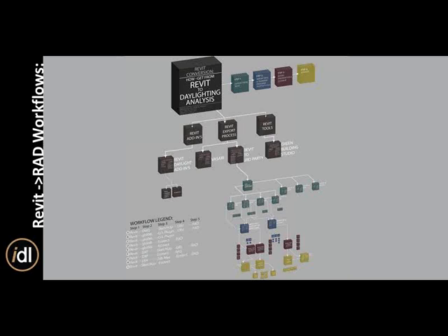Yeah, it's interesting. Opening up the gbXML file, there's only a certain number of parameters that get exported from that material layer in Revit. And Lauren showed like 5 different tabs of properties, right? So it's inherently a simplification that just currently doesn't include surface reflectance, which is the most important thing that we would need for daylight simulation.